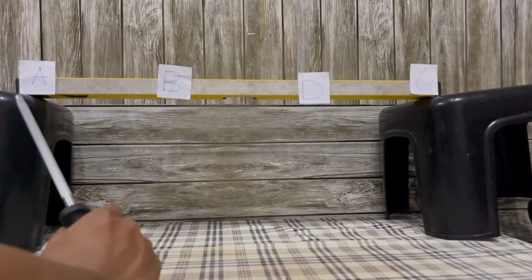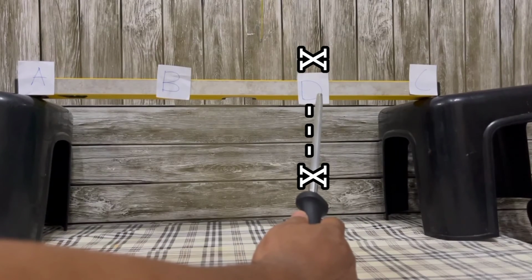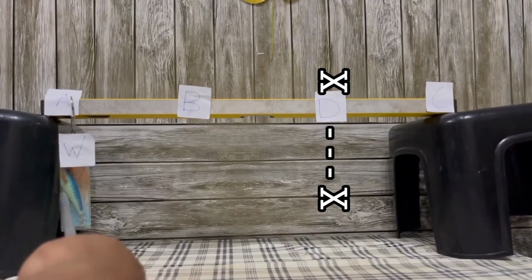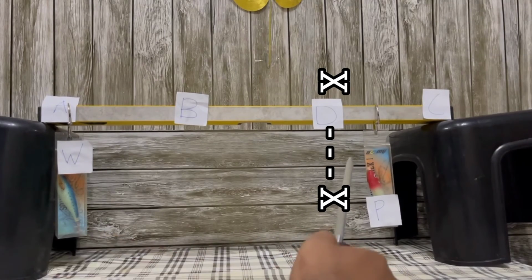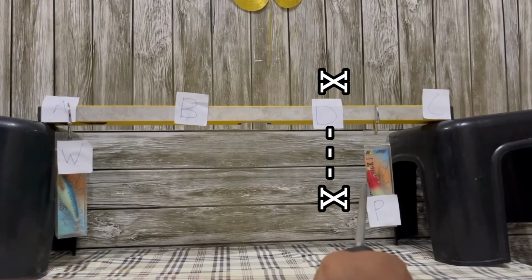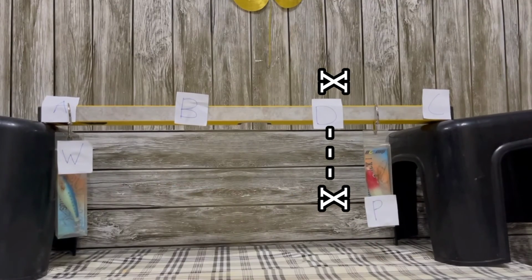This is point A, point B, point C, and point D. The section XX is at point D. The first step is to put the load W at point A. Then we put load P between point C and point D. Next, we measure the distance from point C to load P, and then we get the bending moment at section XX, which is at point D. Lastly, we compare the theoretical value, which is the calculation, with the experimental value.